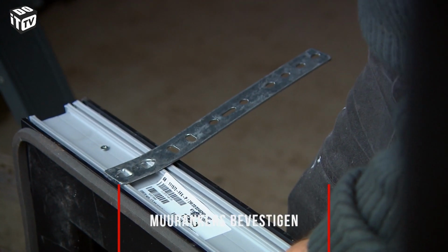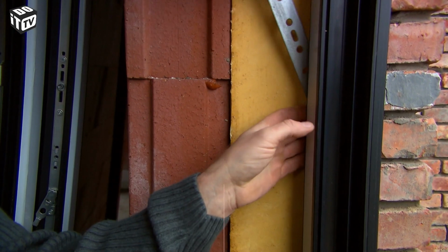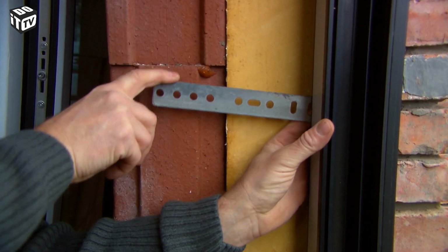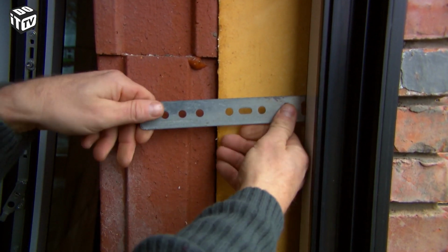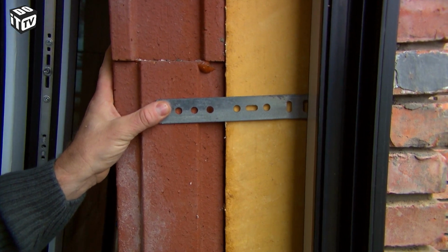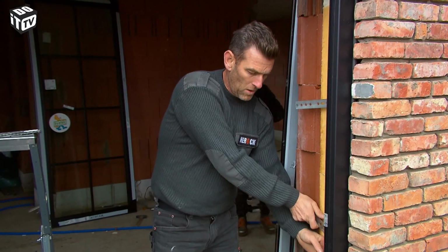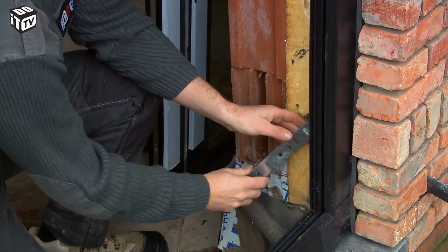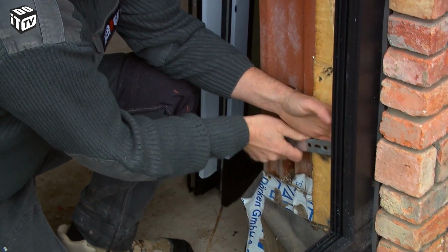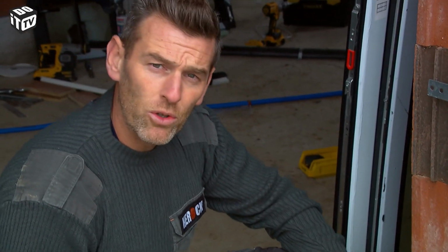You click the wall anchors into the provided slot on the framework with a twisting motion. The frame has already been installed, and then you click the anchors onto it. To get the anchor closer to the wall, you manually fold it for a moment and then push the whole thing closer to the wall. Ensure you add enough hooks so your window stays well secured.